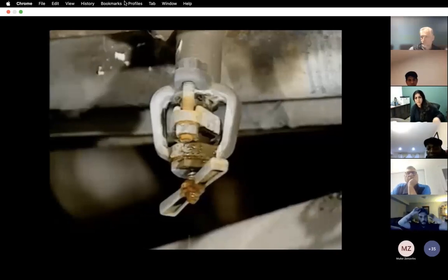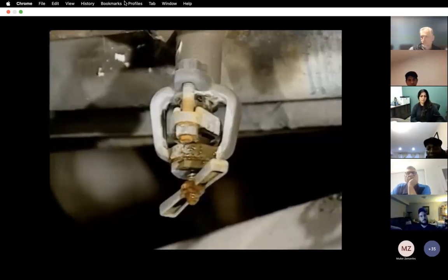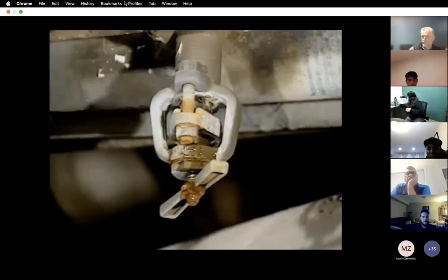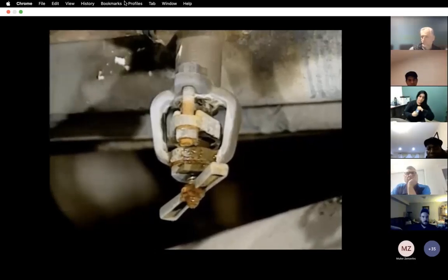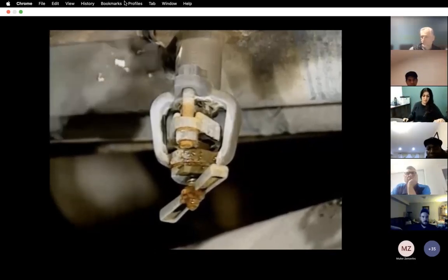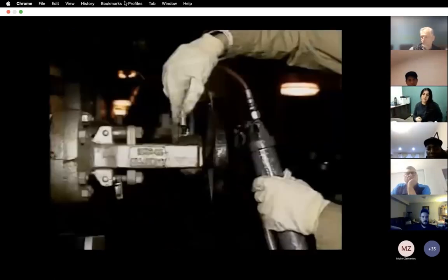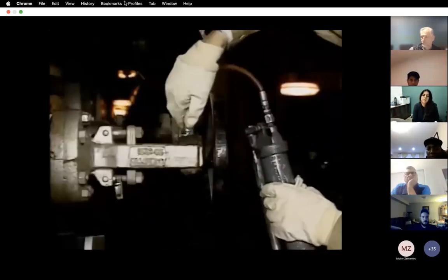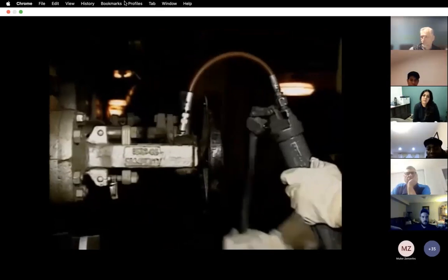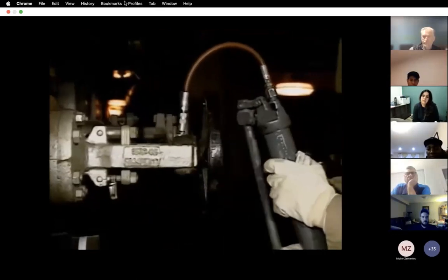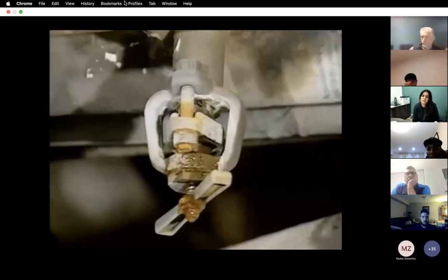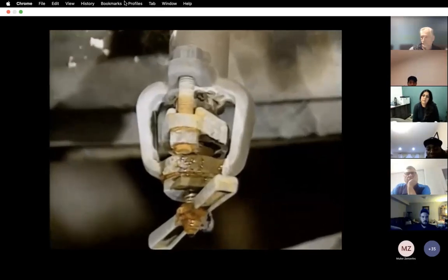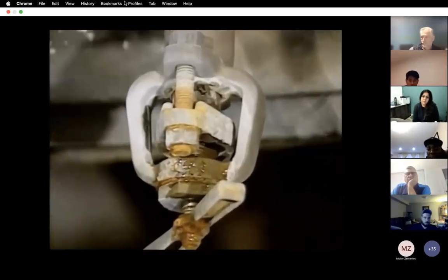Valves, like many other components, require some routine maintenance and are susceptible to mechanical problems. In this part of the program, we're going to take a look at one type of valve problem, a leak. Then we'll look at a routine maintenance task that an operator may have to perform to keep valves operating properly. If a valve's packing becomes worn or fails completely, fluid will leak out around the stem.